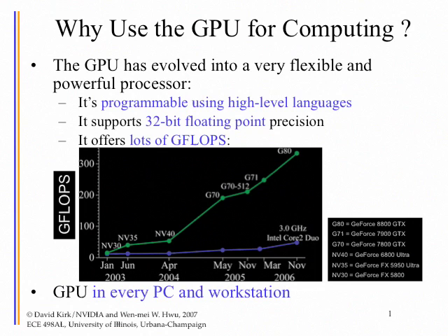And the reason why these chips are running too hot is because CPUs have been designed with the philosophy of very high clock frequency. And whenever you run the clock frequency at a very high level, you need to be able to drive the current very quickly, so that consumes power. And also, the actions happen very quickly, so you do the switching more quickly. And these things multiplied together give you a huge amount of pressure in the power management.